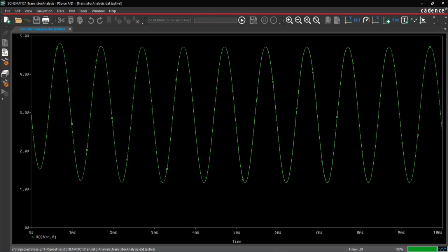Even if we have set our cutoff frequency to 300 Hz, due to imperfections of RC circuits, even a signal with 1000 Hz frequency will be slightly attenuated, but not by much. This is totally acceptable output. If you want, you can plug in different values for AC signal frequency and observe the output. Just don't forget to scale both X and Y axis in order to get proper and true scale for signal display.